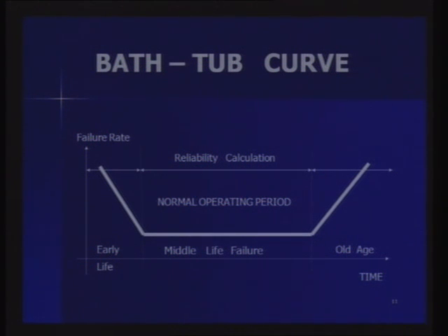The purpose of maintenance management is to extend this middle life or normal operating period. How long we can increase it through our maintenance management activities, we try to increase this period, and ultimately one day this equipment or component is going to fail. So this is a very important curve which we have borrowed from human life and applied to plant, equipment, or components of any product.